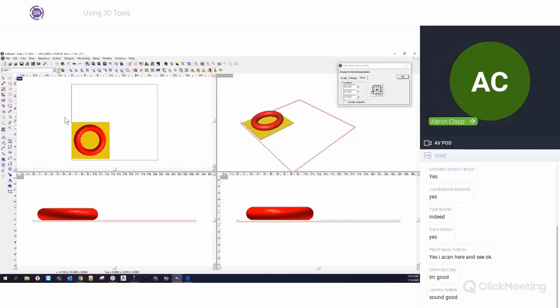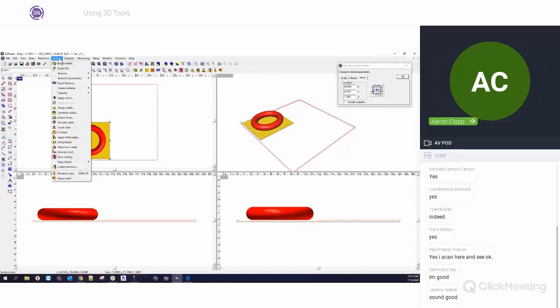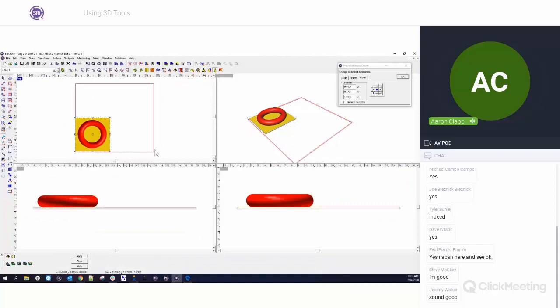So it's really easy to get this mesh into a relief. We select the relief that we created, the flat relief, and the torus, or the donut, and then we just hit this little diamond up here, apply mesh to relief. You can also find it under the surface menu. It's right here, apply mesh. I click on that, and that will simply give me several different options down here.